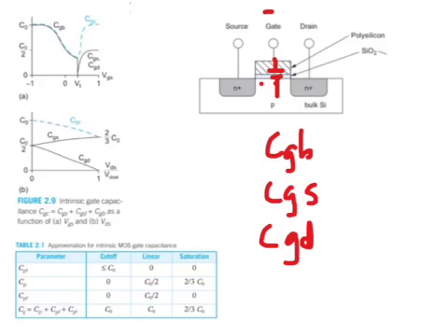As an increasing positive voltage is applied, there starts to be an accumulation of free carriers drawing closer and closer to the oxide layer, and this tends to reduce the capacitance levels seen between the gate and the bulk semiconductor, because you can think about this as the parallel plates of the capacitor actually coming together closer, and this corresponds to this decrease here, in this direction.